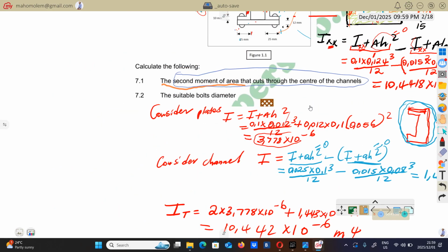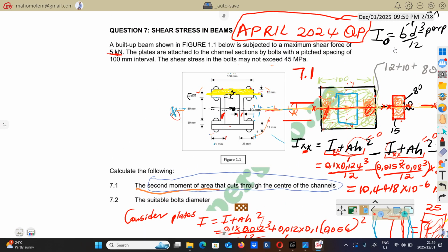So from the first video, I illustrated a scenario of double shear. So this one, if the bolt is only used to join two blades together, then we're going to have the single shear. This bolt will experience a force in that direction and then in that direction at this point only once.